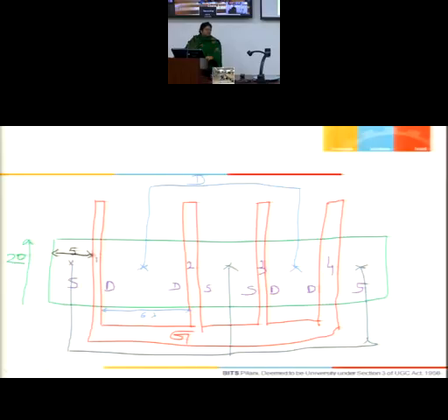And Vasanta? Yes, Apurva. So what I feel is that everybody should know how to calculate, and then your task will be to draw the layout in your lab and actually calculate the capacitances and obtain them through simulations also. You should obtain the capacitances in SPICE. Everybody is using ELDO? ELDO, or you are using Spectre. Whichever you are using, you have to estimate the capacitive effects. So this is one way of reducing parasitic capacitances.